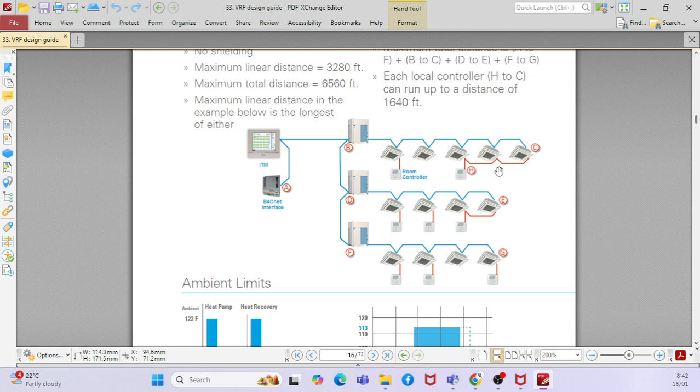Yes, but that was a confusion that I also used to have. But then at that point, when you choose your system, do you just choose typical terminal units and close it off? No, see, normally, I will tell you, there is some option in the HAP. If it is chilled water, go with the chilled water system, because you have to enter the delta T, chilled water supply and return.